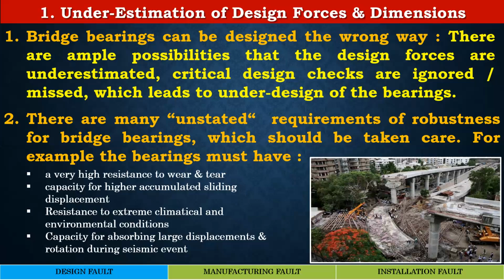which means you had to anchor the bearing. You had to provide a tensile bearing, which will hold it against toppling. But instead of that, if you design it as a straight bridge, you will get compressive force and you add 25%. That means you have provided a completely different type of bearing than what is required. And this is precisely the reason why this particular span collapsed. So it is a good example of how the ignorance of the designer can lead to this kind of mishaps.